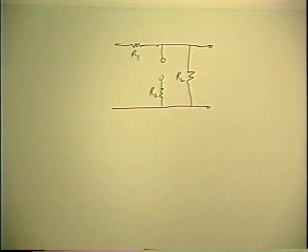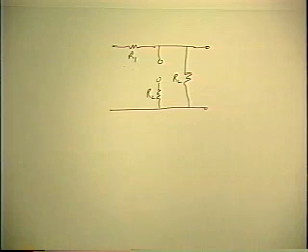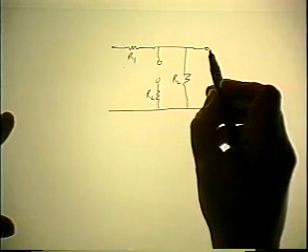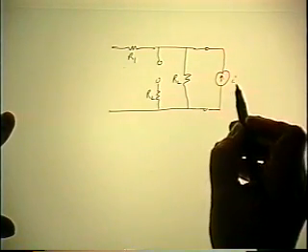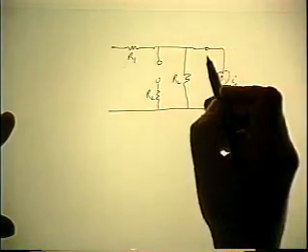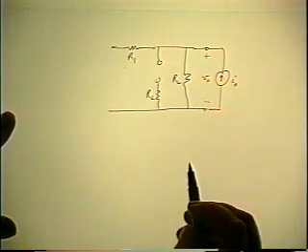And the first thing to do is to identify correctly input and output. The function we're correcting is output impedance. So we're going to drive the output with a current, which I'll call IO, and we're going to develop a voltage across it, which is VO.